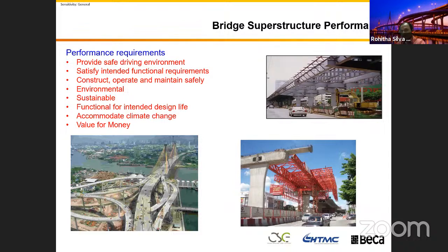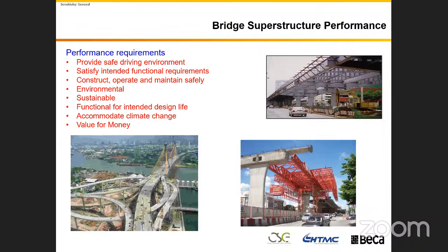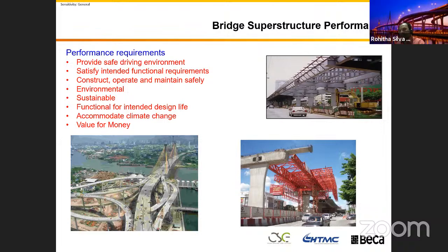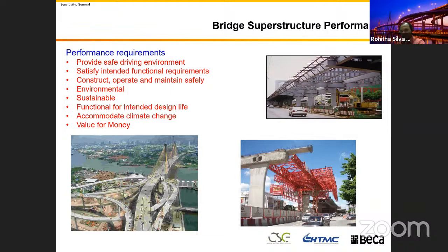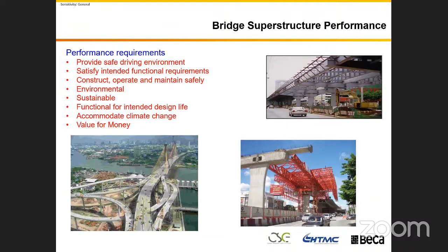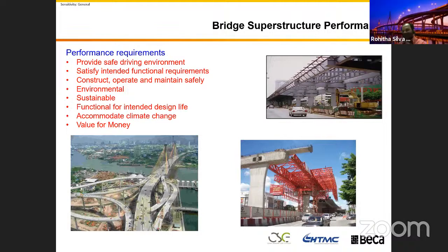Even now, the Australian standard is AS 5100, latest revision. It limits that if the concrete thickness of any member is greater than 500 mm, you have to do this analysis. That's stringent. Before it used to be 1.5 meters, then it became 1 meter, then 500. In addition to that, we design the mix and control temperature. We also use special formwork systems like polystyrene, and curing, all those things in the durability design.